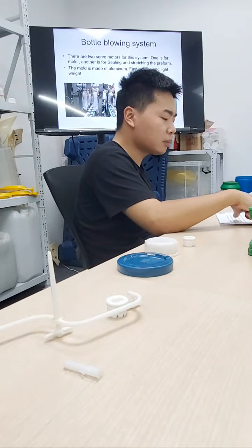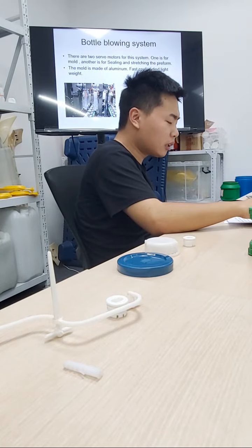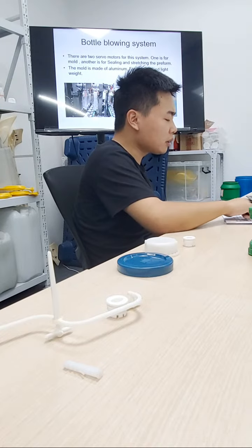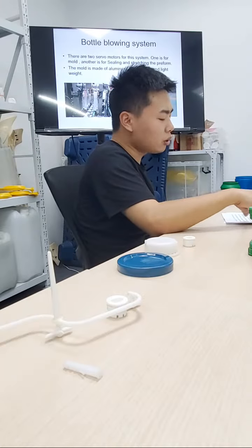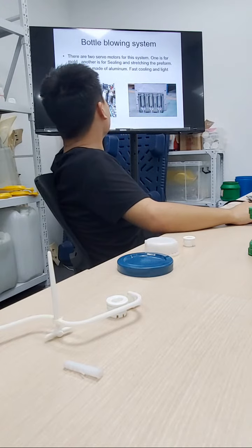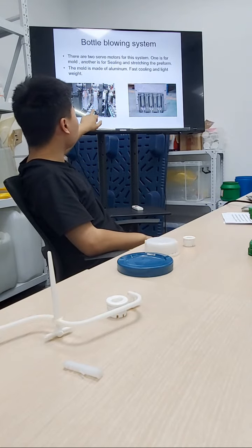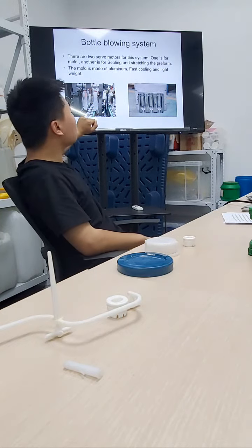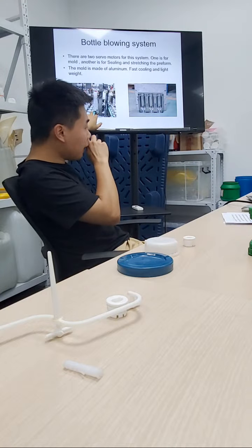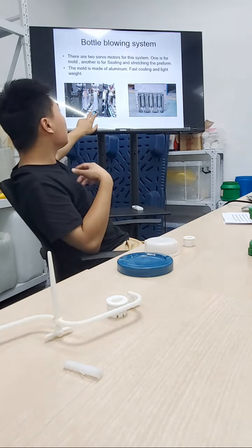The high pressure gas is blowing out, which makes the preform formed. The mold is opened and the chain takes the bottle out. When the chain comes to the end, the gripper takes the bottle off the chain. This is the full automatic production process. This is the mold. When it is clamping, the chain's bottom will set and blow the air. It has two blowing systems. One is the low pressure air blowing system, and one is the high pressure blowing system.